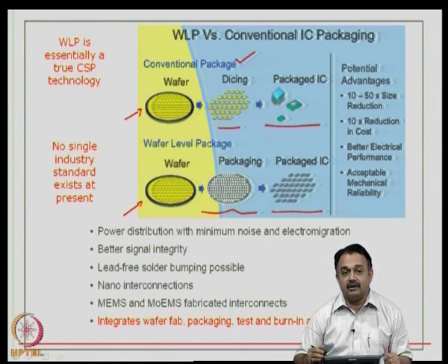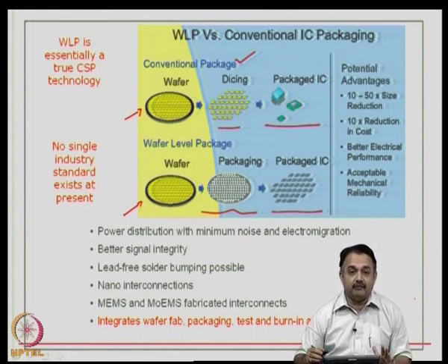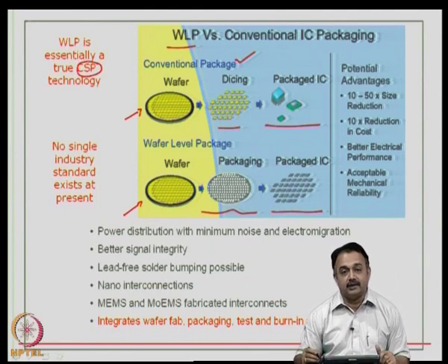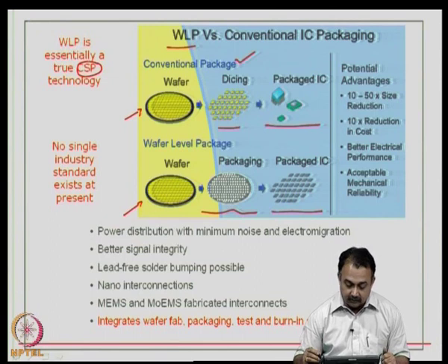But there is no single industry standard that exists today for wafer level packaging, because there are very few players in the global market for manufacturing wafer level packages. So, when you talk about wafer level package, essentially you are going to create a CSP package, chip size package. That is the best thing that you can generate from a wafer level packaging. You are not talking about low density packages.